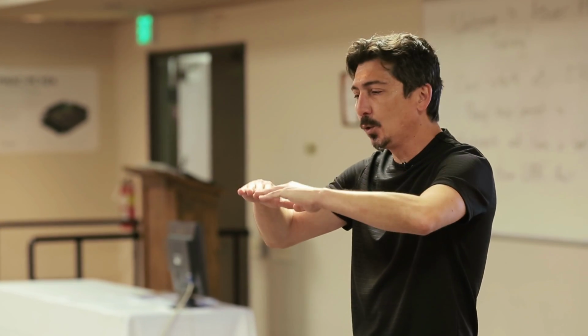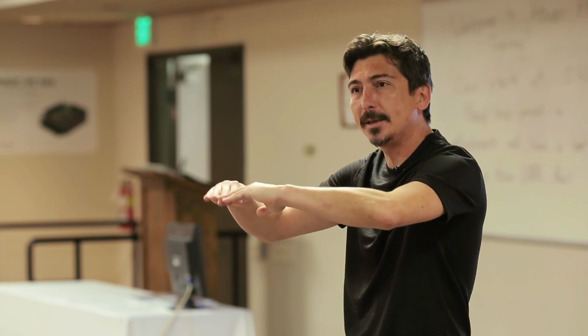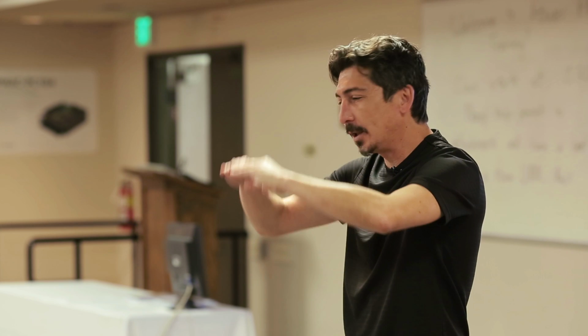But they had a problem. They need to move at really high speeds, and there was a huge acceleration in Z. Although it doesn't seem that they're coupled, due to the fact that there's a guide rod over here, the acceleration actually creates a resonance here. And it starts shaking at more than 500 milli-Gs. And they have some specs for that. They need to get it to less than 50.